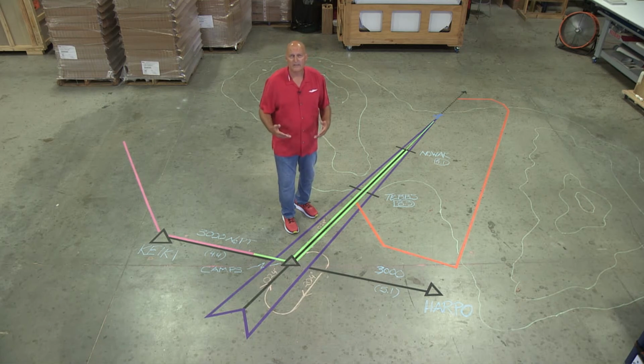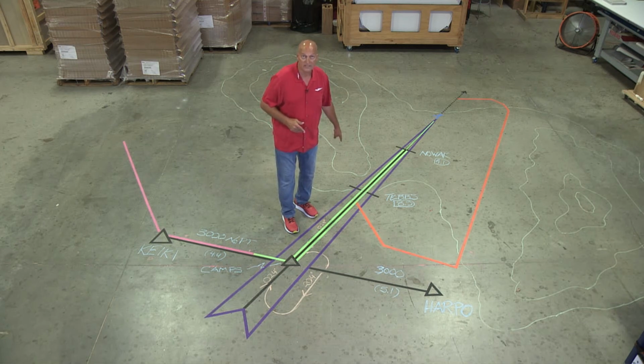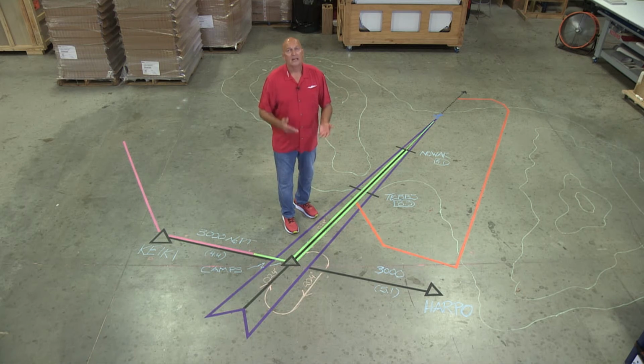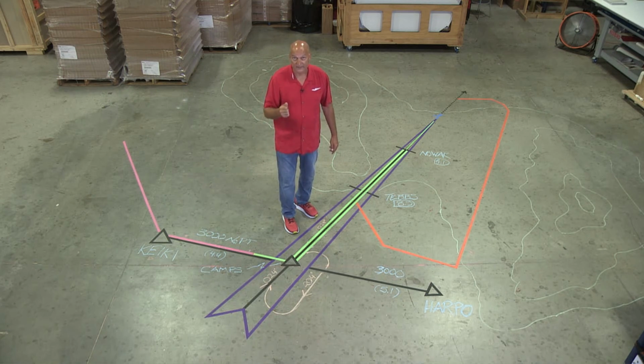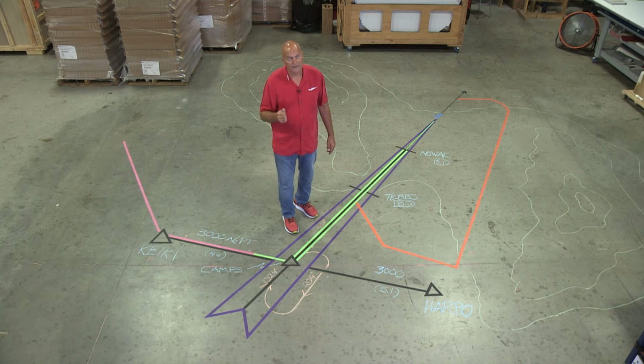And that's a way that they can draw that correlation between a traffic pattern and what they may do here vectors-wise, and explain why they put you on a 45 as you pick this up. 45 degree angle. Number one, when you're hand flying it, it's a lot easier to turn 45 degrees than it is 90 degrees because you've got a lot of stuff going on, but also that autopilot in that airplane, it's a lot easier on that autopilot to make a 45 degree turn than it is to ask it to make a 90 on some of the autopilots that are out there.